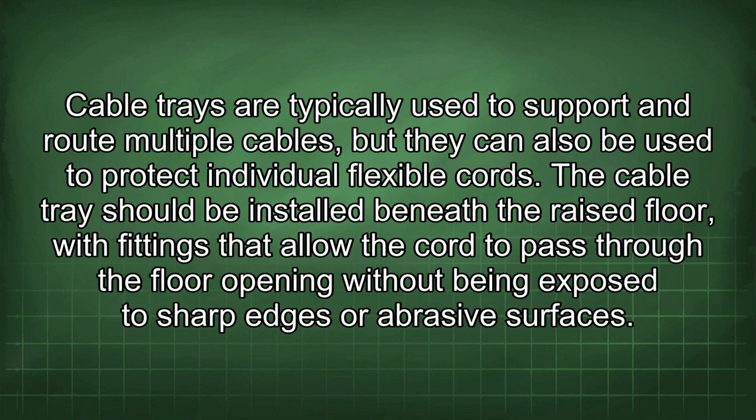Cable trays are typically used to support and route multiple cables, but they can also be used to protect individual flexible cords. The cable tray should be installed beneath the raised floor, with fittings that allow the cord to pass through the floor opening without being exposed to sharp edges or abrasive surfaces.